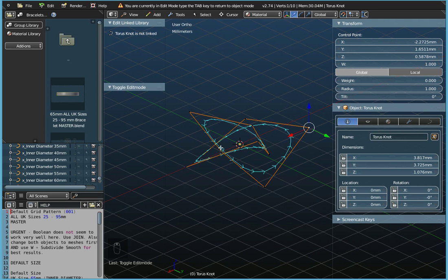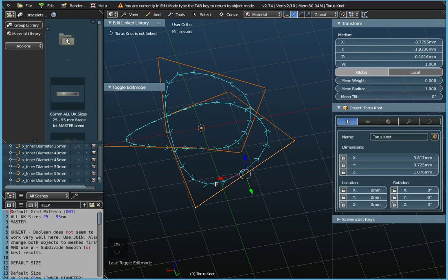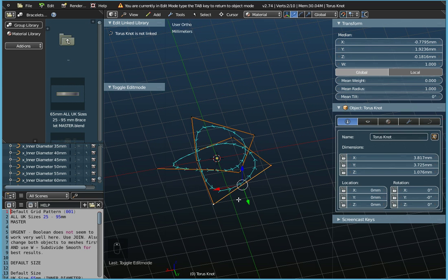So the bigger the resolution there, the more control points that we have around our object. And clearly the more times that we go in and out of ourselves by changing the P and the Q value, the more control points we really need to get a nice and smooth finish. Now we also had a resolution of 4. Now if I just highlight 2 control points there, no, I think actually I had it as 5, I think. So if we look at the blue arrows between these 2 control points, we've got 1, 2, 3, 4, 5 arrows between a set of control points. That comes from the resolution of the surface.